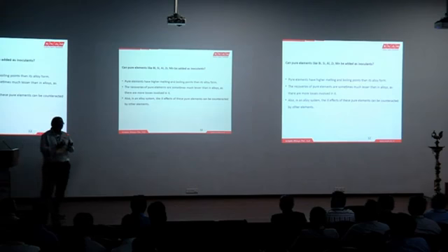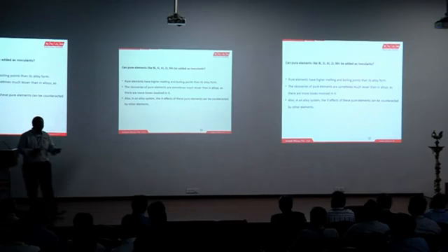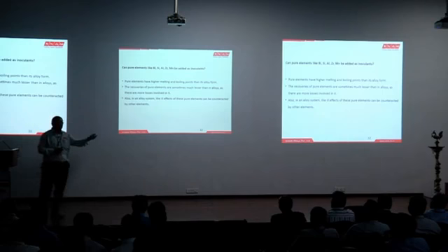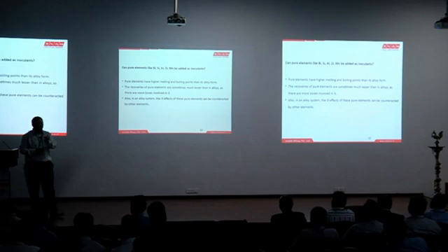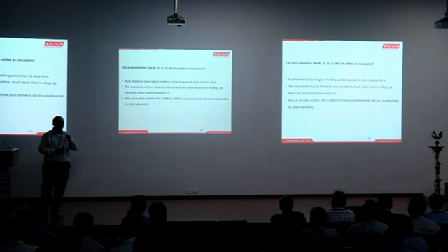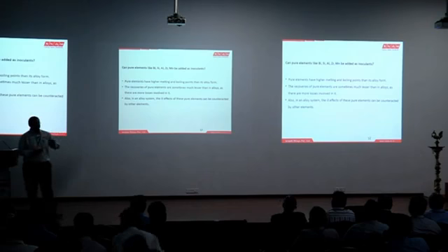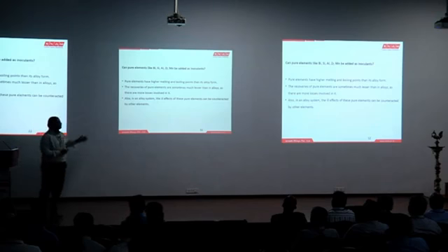Pure iron has a rusting tendency. When you add carbon to it, you increase the castability of iron. When you compare pure iron with cast iron, or iron with excess carbon, it increases the castability and reduces the shrinking tendency, though it reduces the corrosion resistance. So these properties are enhanced by the elements we add as alloying elements. In some cases pure elements help, and in some cases pure elements have their own negative impacts, and ferrosilicon is used as a balancing element for all these negative impacts.